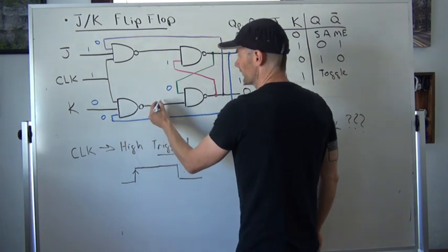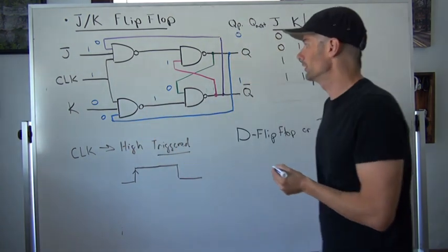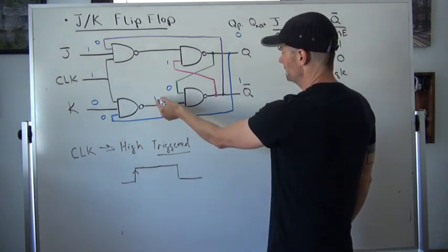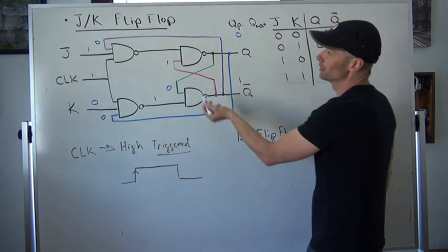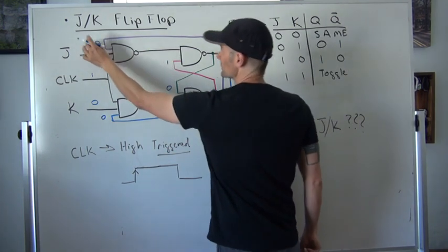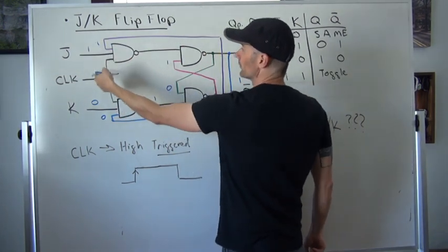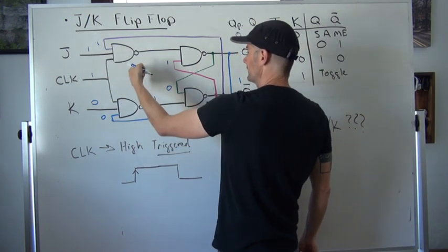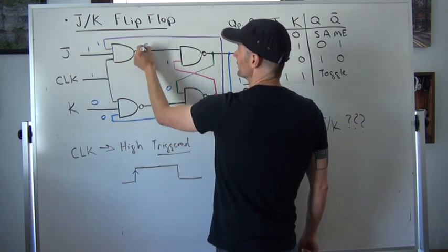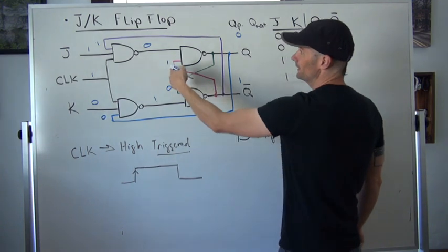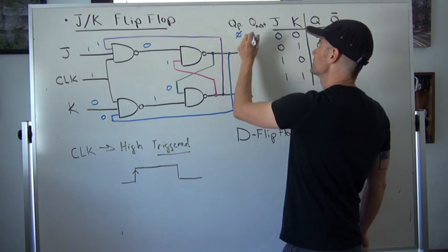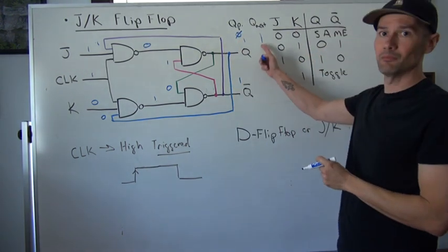So obviously the output of this NAND gate is going to go high. And so if we have 0 and then 1 right here, that holds this guy to be a 1. But if we look at 1, 1, 0, then there's a 1 right here. That causes 1, 1, and 1. So here we get an output of 0. And we know that if we NAND 0 and 1, that causes this output to change to a 1. So Q next actually became 1.